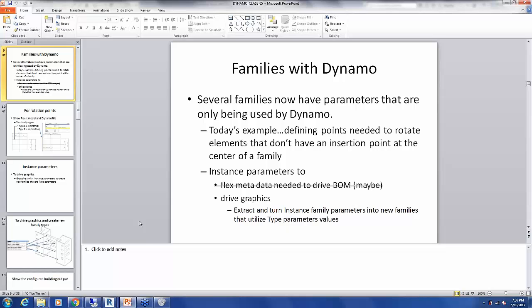already, in this one configuration, you'll see there's hundreds and hundreds of components already. So in order for me to not have to manage hundreds of different families and create hundreds of different if-then statements for Dynamo to select the proper family, depending on what configuration the building is, I've done a big no-no, but it's working out very well for us at this point, is I have like one family to kind of rule them all, right? So I have one door.